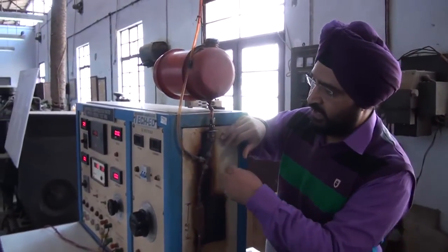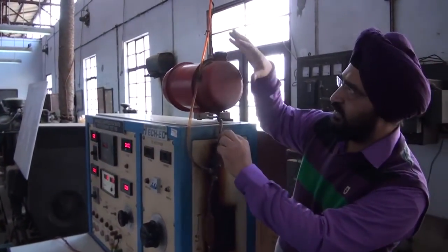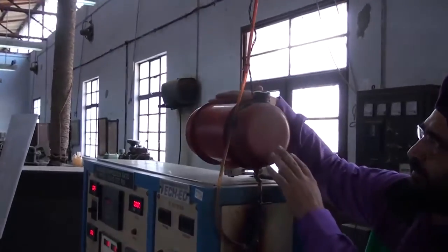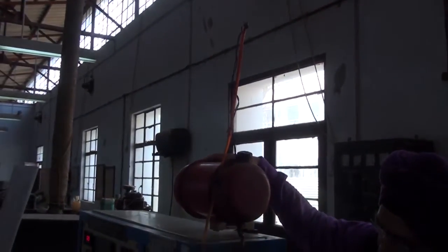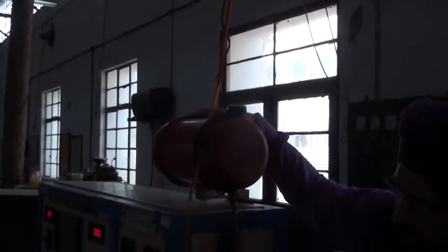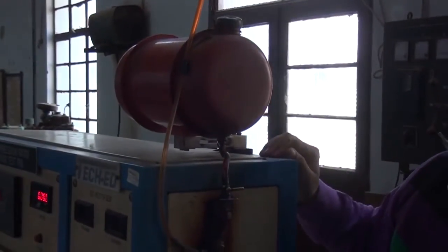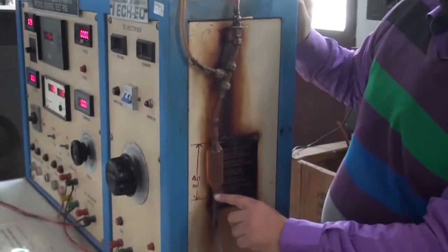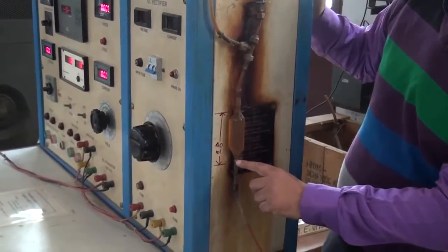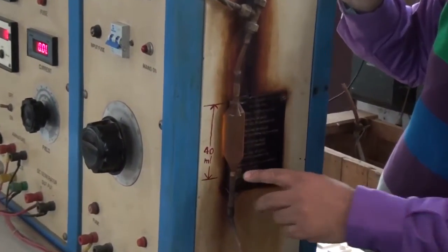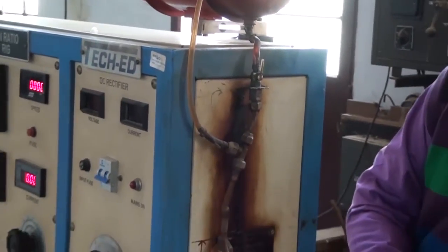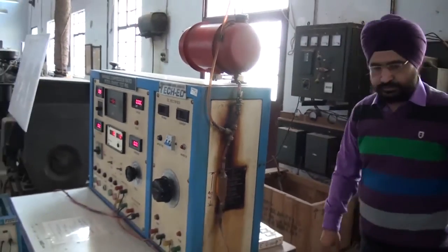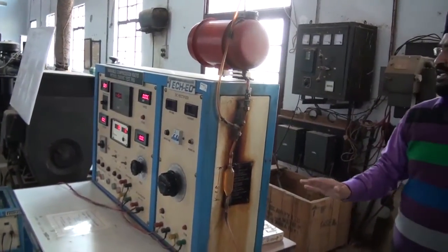When we have to note it down, we'll close the supply from this top tank. This is a top tank in which fuel is stored. We'll close the supply, and now the fuel will slowly move down, and finally it will pass this line. 40 ml is finished. Now note the time, and that is the first reading. So we'll do it again. So this is all about testing the various things.